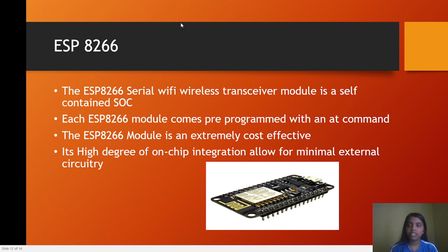ESP8266. It is a Wi-Fi module. The ESP8266 serial Wi-Fi wireless transceiver module is a self-contained SoC. Each ESP8266 module comes pre-programmed with an AT command set. The ESP8266 module is extremely cost-effective. Its high degree of on-chip integration allows for minimal external circuitry.